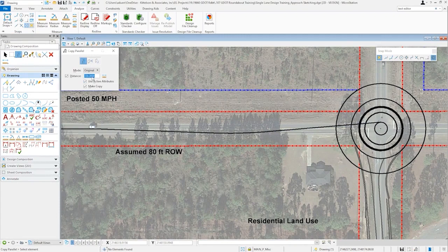I'm going to assume that at the roundabout or near the roundabout, our splitter island is going to be approximately 15 feet wide. That's just based off of my experience. If we were looking at this under a practical design microscope, we may reduce that to 10 feet so that we have a 6-foot minimum width splitter island. In this case, I'm going to assume 15 feet, and that's more or less just a personal preference.